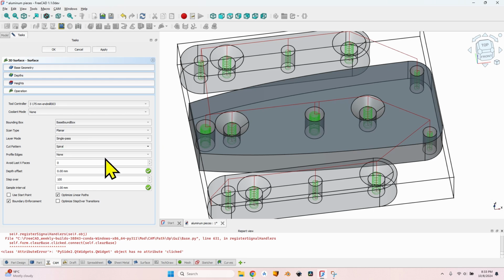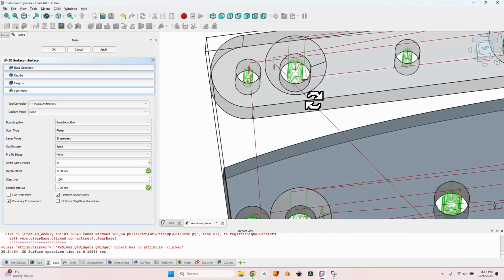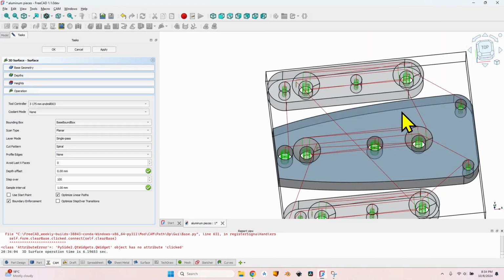This is the most important setting because this way it will move in circles and the resulting surface will be exactly as I want. Now let's test it. Let's click on the apply button and you will see what I was talking about, why this approach, selecting all these faces, doesn't work. Well, you can see that instead of a spiral in each of the faces, it created a huge spiral, I believe.